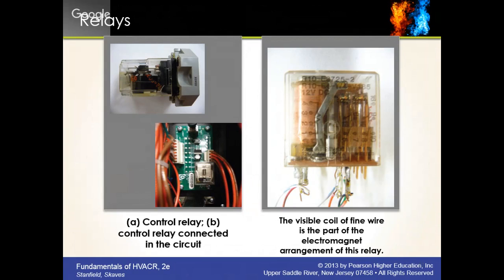What's the difference between a relay and a contactor? A relay is going to be used for the switching side of things. It's going to be used as a switch. A contactor is going to be used to control the load, right? We see the contactors on motors, heating elements, big loads. A switch, like a relay, could be considered off of maybe a thermostat. Something that's going to deal with the signal side of things. Yes, sir.